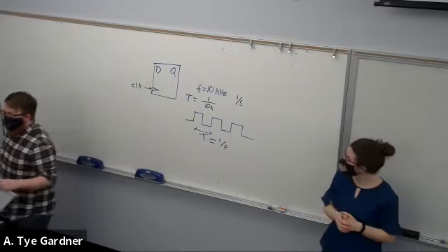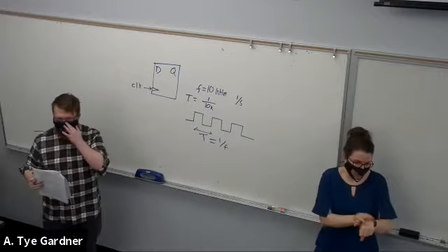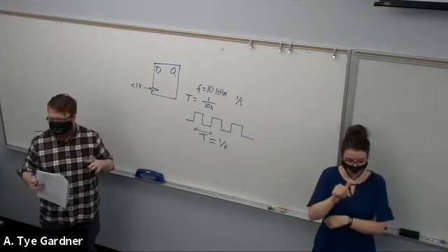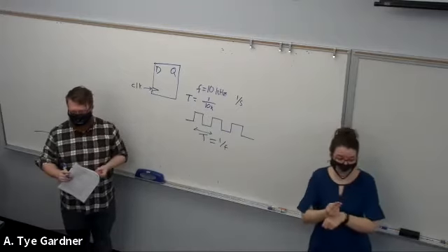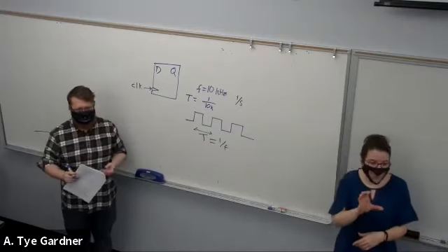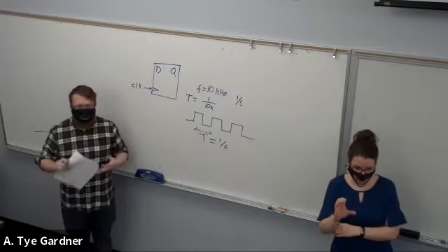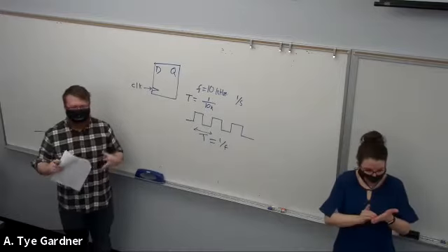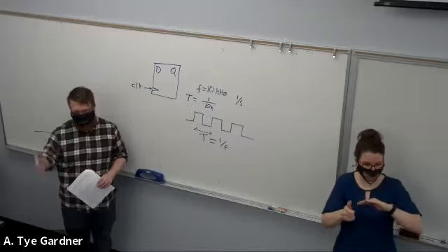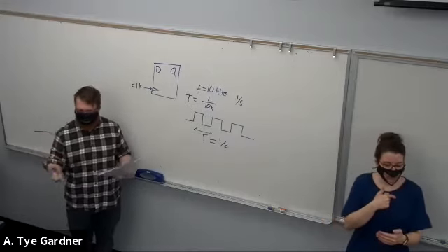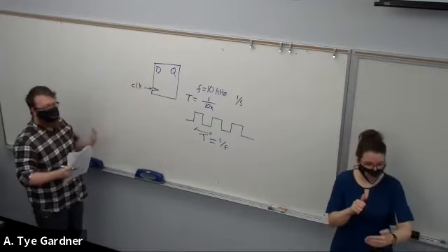A lot of times we're going to have a really fast system clock. For example, the FPGA boards that we're going to use in an upcoming lab, lab 7 or lab 8, have an onboard clock of 100 megahertz. It's very, very fast. But we're going to design a garage door opener. We don't really care about a 100 megahertz clock on something that takes 4 seconds or 10 seconds to close or open, right? Garage doors are not fast. So 100 megahertz is just ridiculous. So what you may want to do is slow down the clock.